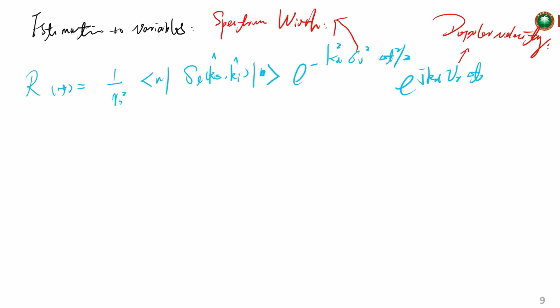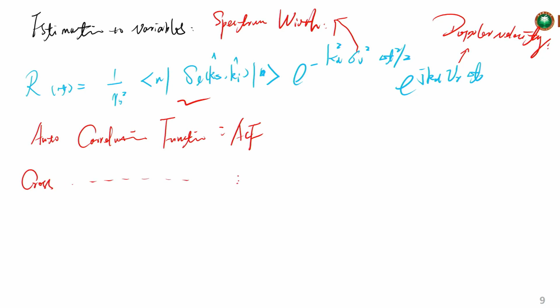Okay. Now from this equation we can see that the correlation function of the weather radar signals follows the Gaussian function also, because it's related to the scattered field here. So now it is extended to include two kinds of correlation functions. Previously we learned the most commonly used one is the autocorrelation function, named ACF, and now we use the cross correlation function, named CCF.